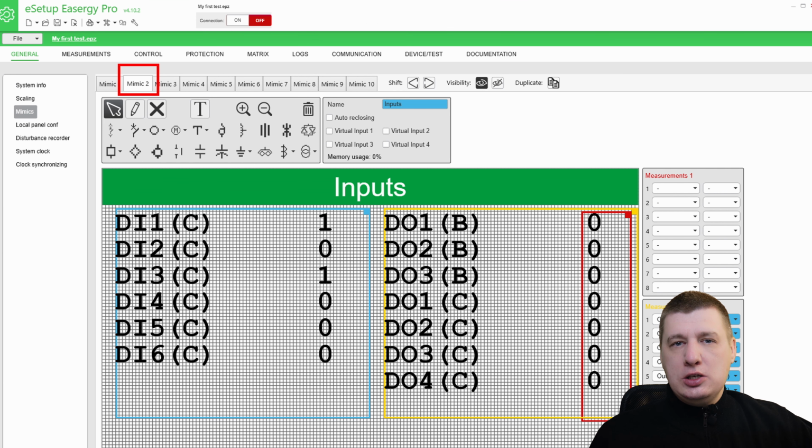This screen shows how to visualize digital inputs and outputs on the mimic page. During testing and commissioning, you need fast feedback. The mimic view gives you live binary states without opening detailed menus. The mimic page shows you digital inputs and outputs in real time. Value 1 means active, value 0 means inactive. Correct measurements assigned turn the mimic into a fast test tool.